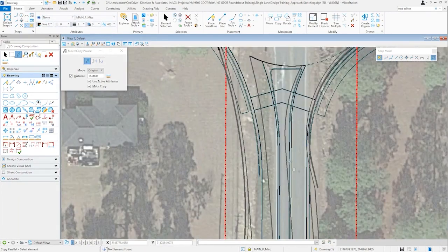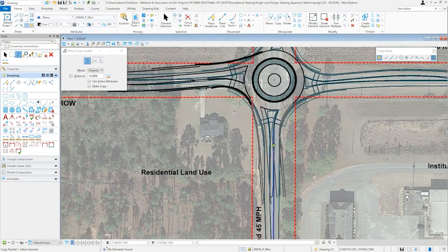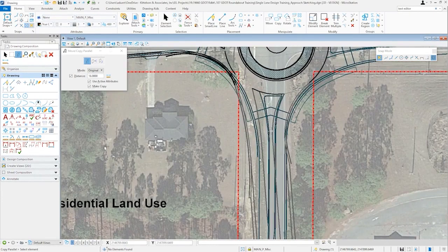Similarly, on the exit side, again, this is a more narrow right of way. So this splitter island is actually shorter, and this approaches a town, so the splitter island length was reduced because of slightly lower speeds and development that will be occurring in the area. Again, the entry side lines up pretty well. The exit side is significantly different due to the much wider splitter island. So on this leg, we may want to look at tightening that up as we look to refine our alternatives.